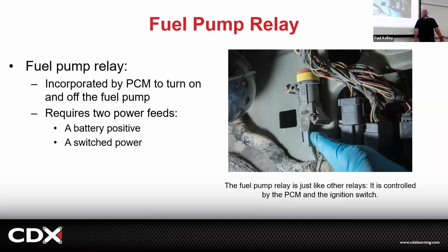They're not doing too much of that anymore. Now that it's computer controlled, your airbag SRS module, the supplemental restraint system computer, will say on the network, hey, we just got hit. Deploy the airbags first, and secondly, don't tell the fuel pump to come on anymore. So now we can do it electronically, with the computer. But back in the day, we had a mechanical inertia switch that would actually trip. It's just kind of fun. But now we're mostly all electronics and we're using this relay.